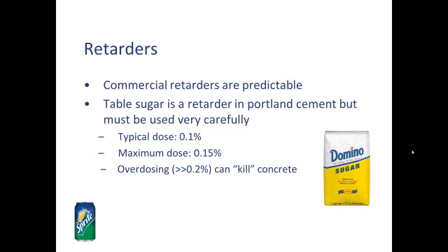Okay, what are you using the percentage? What is the measurement? Again, percent means weight of admixture to dry weight of your cementitious. It doesn't matter what the number is. It doesn't matter what your units are. It's always weight of admixture to weight of dry cementitious. Mils are volume. Pounds are weight. Kilos are weight. Grams are weight. So it's not volume, it's weight.